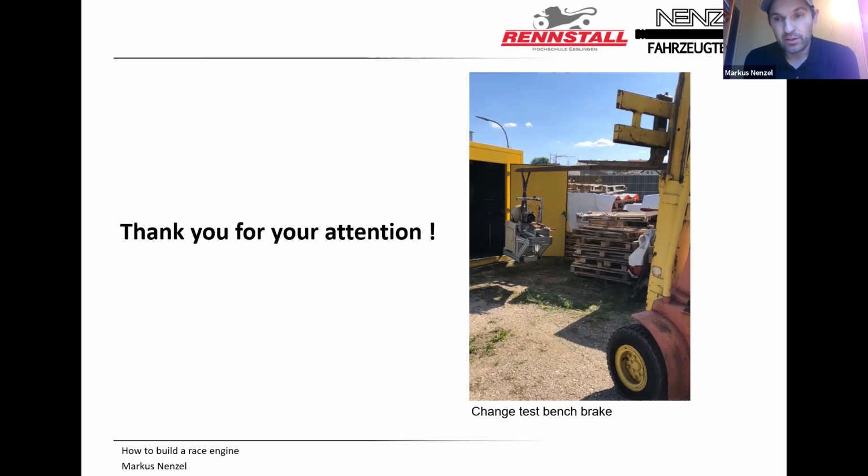In my opinion, you, for example, choose a good base engine, because it's from the package and it's lightweight and maybe it's available and not so cheap. And you have this base engine. Then you make your base calibration. I don't know, the ECU doesn't matter. And maybe the most important thing, in my opinion, is that you have a sure oil pressure, because if you have good oil pressure, you don't burn down your engines.